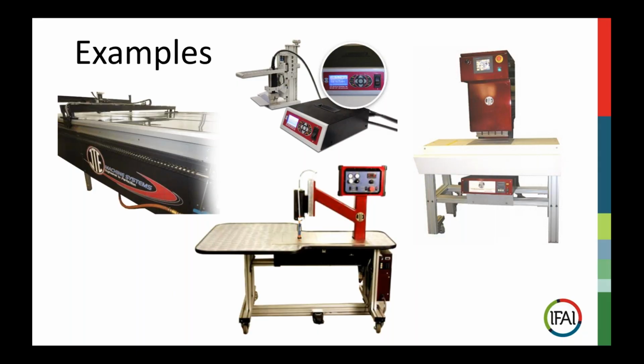On the middle top, you see our handheld, and that is, again, very handy in tacking, small format welding, and everything in between. On the right is the sonic bar welder, which is, again, fairly unique, but here you can weld about 11 inches, and that's about the max of a reasonably priced generator that you can weld, 11 by ½ inch. And then on the bottom, that is the example of the machine welding the bulletproof vest. It's welding and cutting at the same time, much like a sewing machine, but with very little skill needed and, of course, no thread.